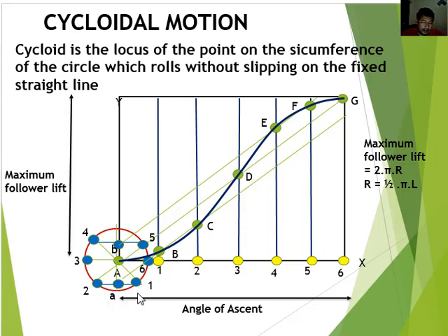Then divide the angular displacement of the cam during the stroke into the same number of equal even parts, the same 6 parts like this.